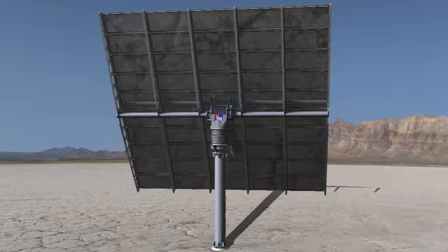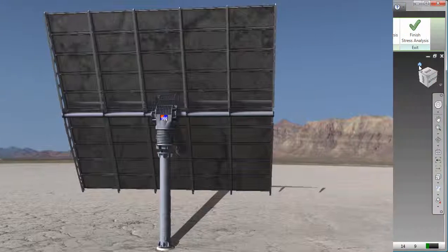This value is based on the expected operating conditions. Wind loads are the biggest loads these products will experience. In their harsh and windy environment, the solar arrays act like a big sail. Equipment loads themselves are usually only 4 to 5% of the wind loads, so if you meet the structural requirements for wind, all other requirements will be met.